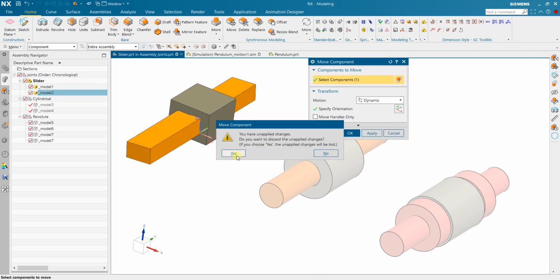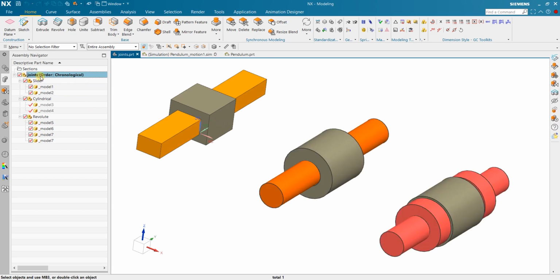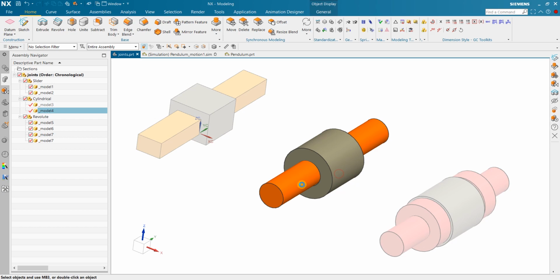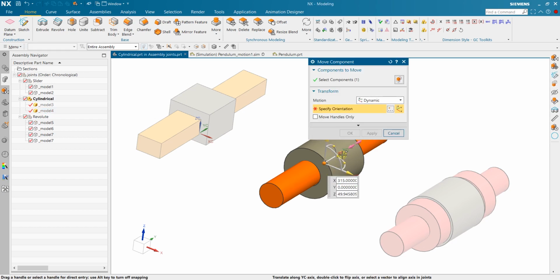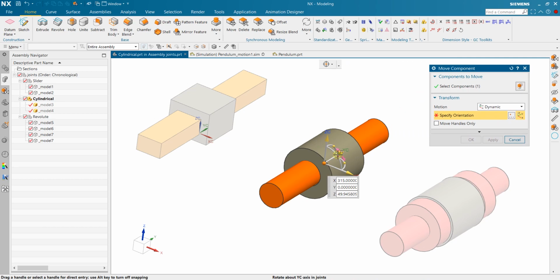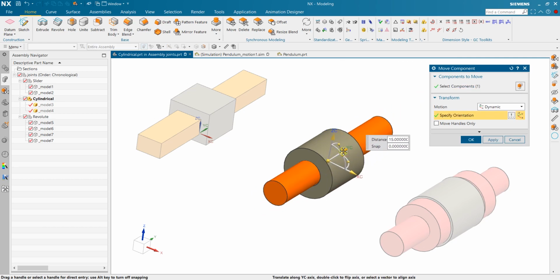Then we have the cylindrical joint. Here, this is a cylindrical joint, and it's very similar to the slider joint, but it can take the rotation along the axis of the joint. So the movement can be like this, and it can also rotate. Here the shaft is uniform, so you don't see the rotation very well, but it can rotate without any problem, as you would expect. And it can also slide. So there won't be any reaction force generated when we rotate it axially.